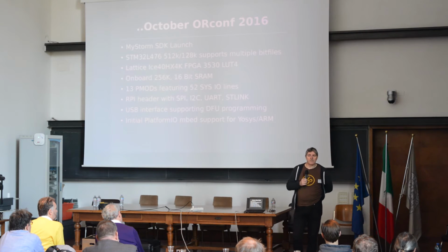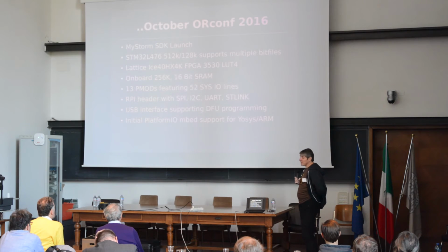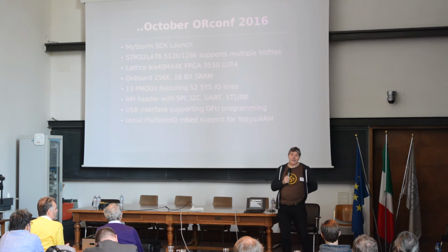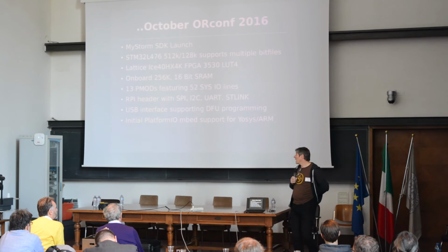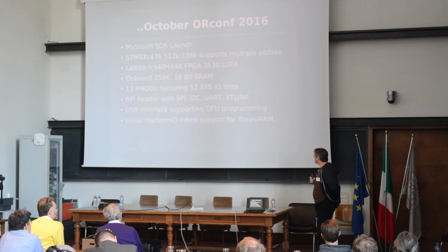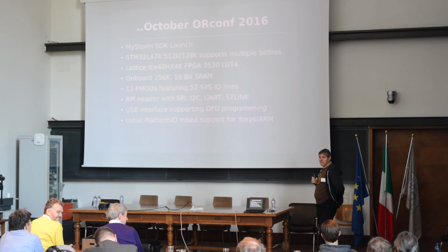Actually, the hardware is an 8K die, we understand, and we don't believe that it's disabled or limited in any way. So if you're using the IceStorm tools, you will find you actually have access to about 8K, 7,500 lookup tables rather than the 3,500. Worth remembering. That's a nice little bonus.